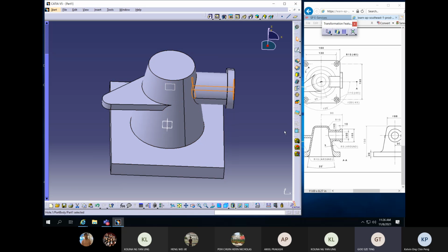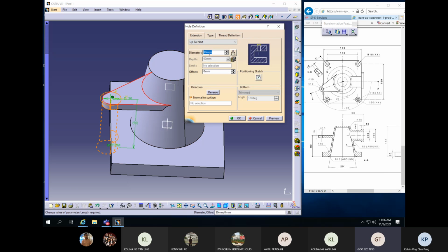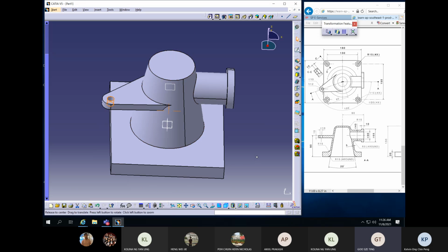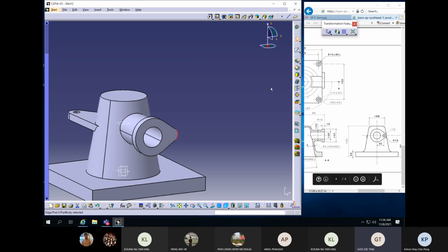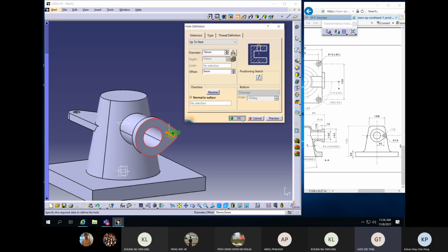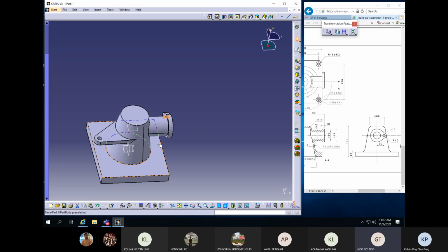Then the circle wise now, here the circle is about 10 diameter. Same thing, share the same center, hole position, cut here. This one is 10 diameter, and up to the next preview, then cut the hole, say okay. Done. Now the hole here is 10 also. Same thing, share the same center. Hole command, click here, 10 also. Finish.